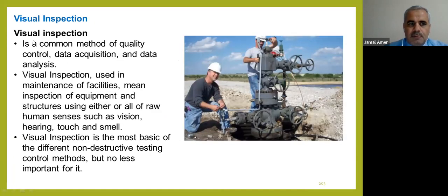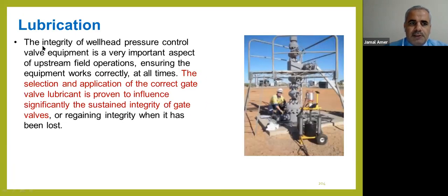We also have visual inspection, as we said, and lubrication, to grease the valves. Greasing should be done after any job, mainly if we have an acid job, to avoid the bad effect of acid on the valve internals.